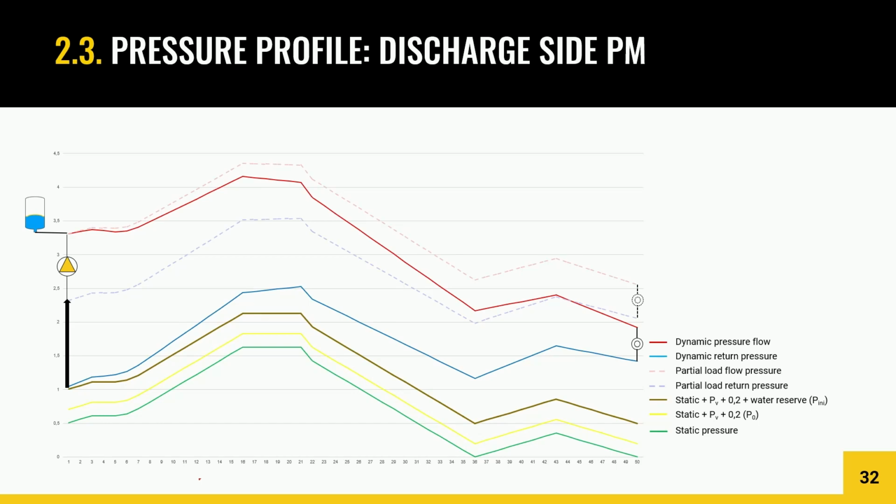Now, with the vessel on the pump discharge side, the discharge pressure is held constant, so this pressure is constant. That means when the pump reduces speed or reduces head, the discharge pressure stays the same. So this pressure stays the same, while the suction pressure rises. So the pump differential drops, and that means something has to happen. But if the pump discharge can't change, the suction will change. So the suction pressure will go up.